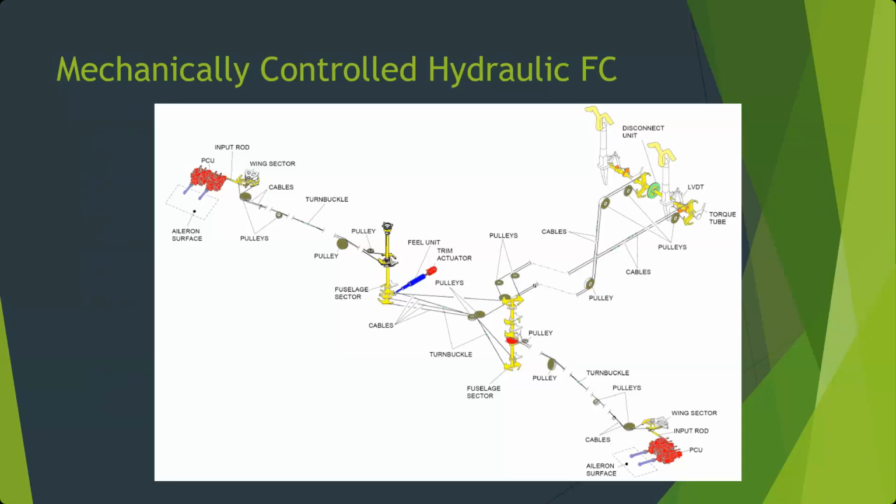But essentially, you have a division because you can actually roll the airplane with one aileron. You don't even need both ailerons to work. You won't have as much of what's called control authority. It'll be lethargic. It won't roll as quickly, but you can still control the aircraft.